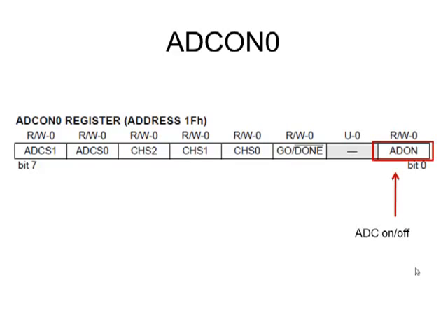Now, you don't always use the analog to digital converter, so if you're not using it in a particular application, you can just turn it off, and that conserves power. A lot of microcontrollers run on battery operated systems, and conserving power is very important in a case like that. So we can save a little power by turning that off.